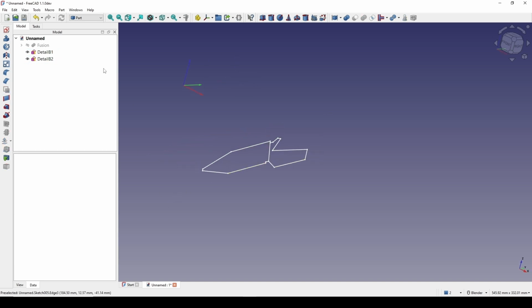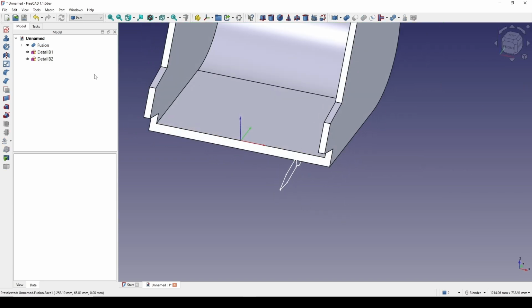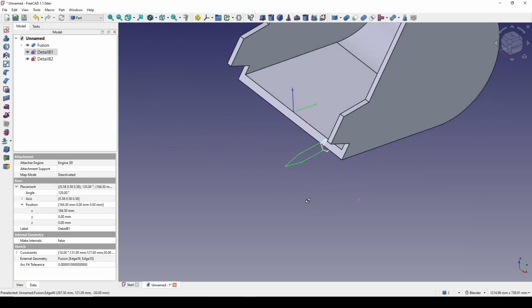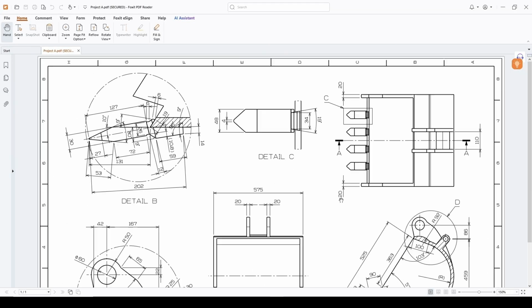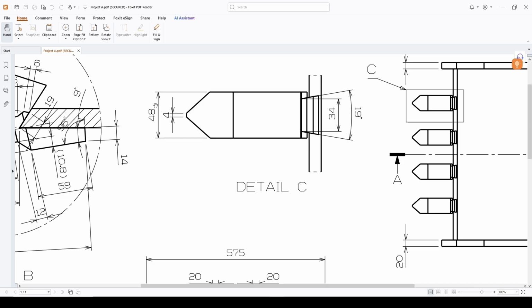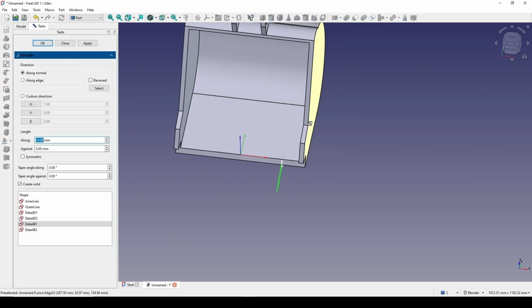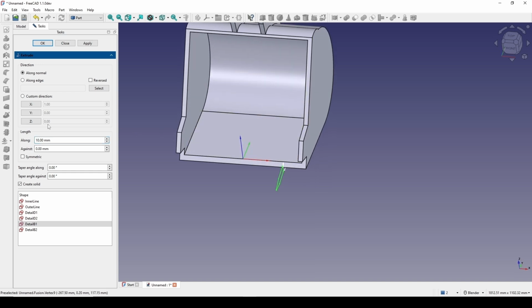All right. Let me show the fusion. Let's start from the B1 first. I will extrude the B1 to 48. I click on this one and go to the extrude, in the negative direction on the x-axis.